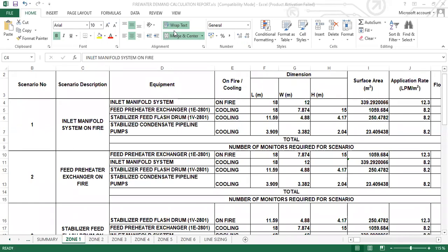And if we set it up such that it's that zone and the other zone that we want the deluge valves to go off in the event of confirmed fire, then that means we need to design for that. But we've currently designed such that it's just one zone. Once there's a fire in one zone, we need to provide protection for that zone. So our firewater system demand is based on finding the zone that has the maximum water demand, and that's the zone we're going to use as our design zone. We are not going to add up zones 1, 2, 3, 4, 5, and 6. We are just going to compare which of the zones has the highest firewater demand, and that's what's going to govern our firewater demand requirements.